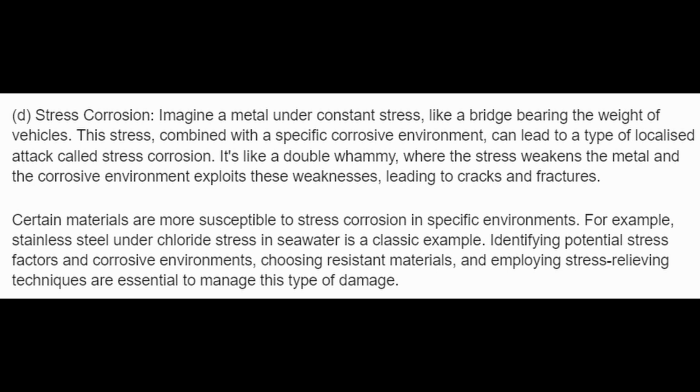For example, stainless steel under chloride stress in seawater is a classic example. Identifying potential stress factors and corrosive environments, choosing resistant materials and employing stress-relieving techniques are essential to manage this type of damage.